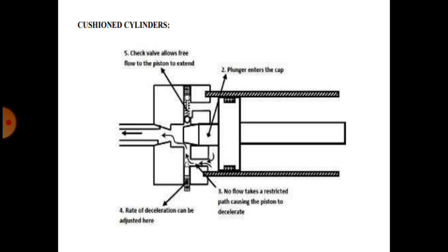So telescopic cylinders, such designs are used where long strokes are required with a short retraction length. For example, the hydraulic jacks used to lift aircraft, dump truck bed riser, and so on. These cylinders basically work on the displacement principle, as explained in the earlier section. Next we will discuss cushioning.